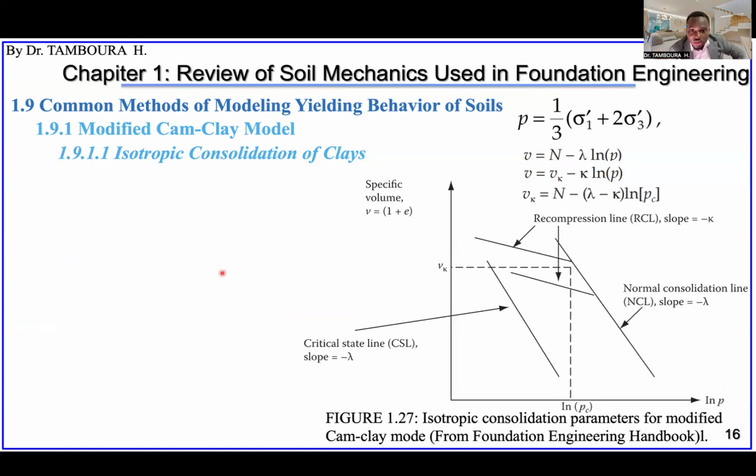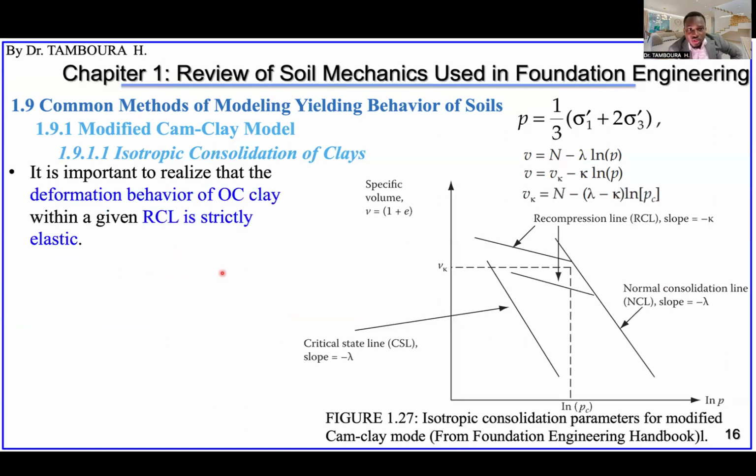That's all. Okay. So it is very important to realize that the deformation behavior of over consolidated clay with a given RCL, RCL is this line, is strictly elastic. This line is elastic because the soil has experienced the stress at this level before.